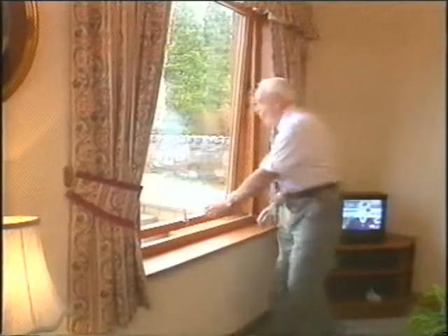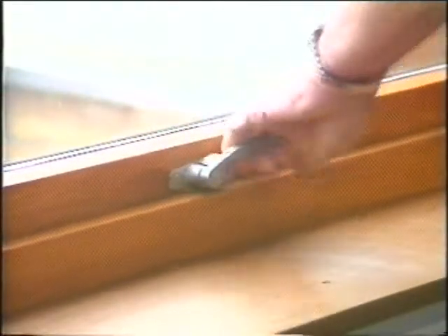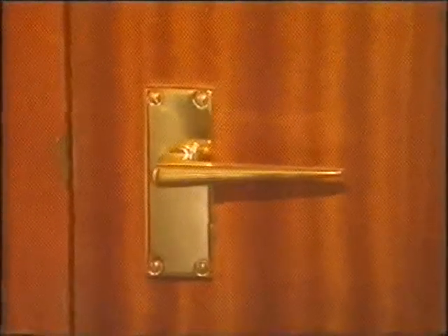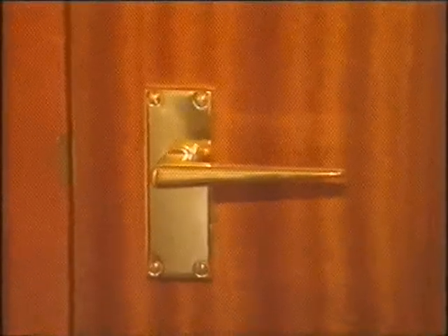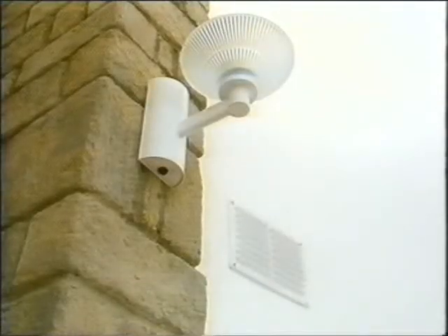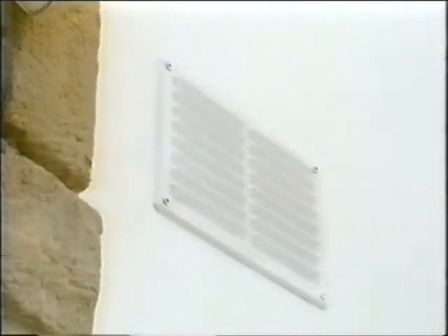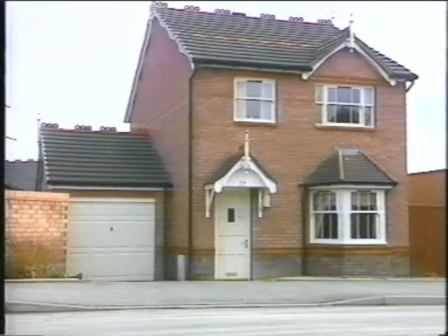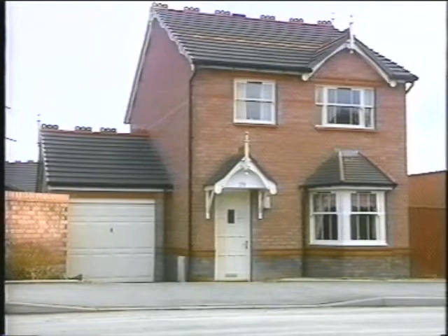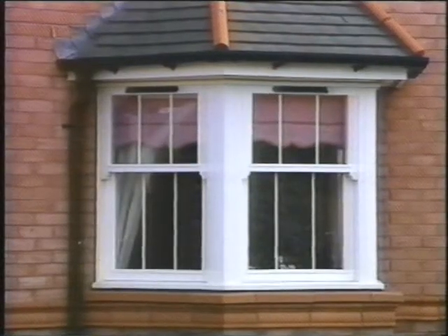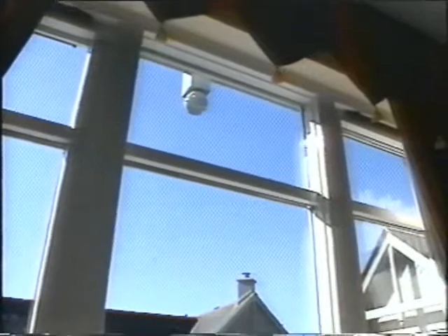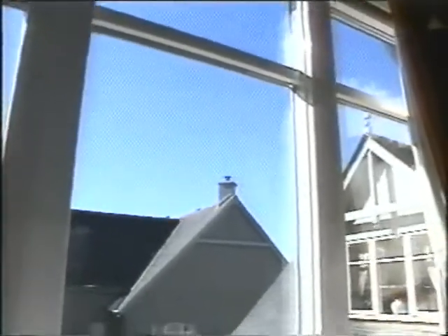Gaps around doors and windows cause drafts, especially when they're on outside walls. All gaps like this should be draft-proofed. But be careful never to block ventilators, grills or any other fixtures which are purposely designed and located to allow air to flow through them. There's no doubt that double glazing does help to reduce heat losses and eliminate drafts. It also helps to counteract the downdraft effect caused by warm air being cooled by cold glass and falling down the wall under the window.